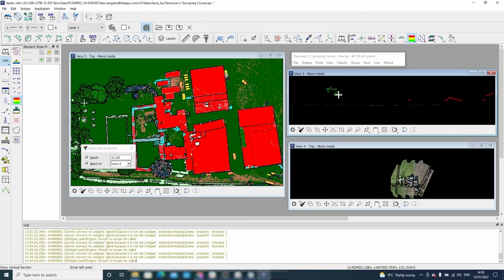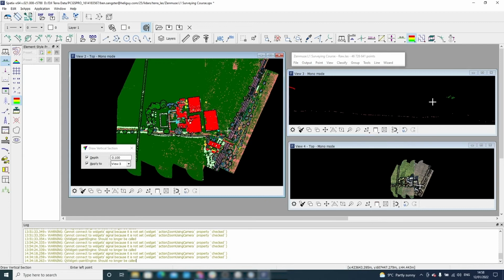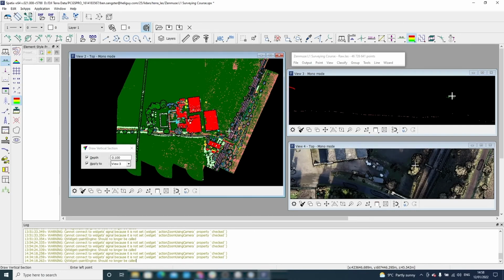It's entirely up to you whether you want to check more of the point classes. Ultimately, it depends on the features in your survey area, so if your project took place in a car park, it would be worth checking the point classification of cars. This concludes our use of the Geoprocessing Wizard for cleaning and classifying our point cloud. As you can see, the process is mostly automatic.